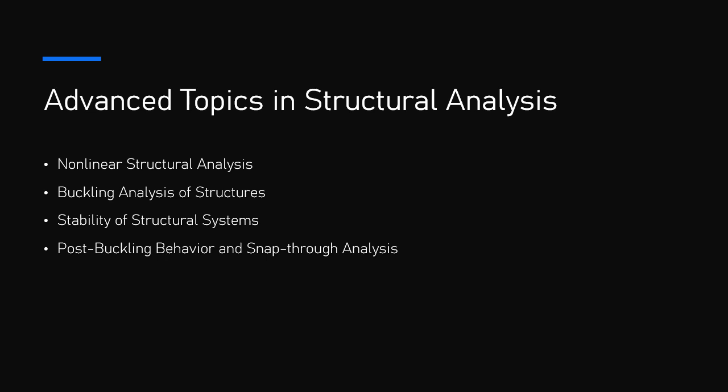Nonlinear FEA allows engineers to model large displacements, material nonlinearities, and geometric changes that occur after buckling. Arc length methods and load-controlled methods are typically used to track the behavior of the system beyond the buckling point and ensure that the path is properly traced in the post-buckling region.